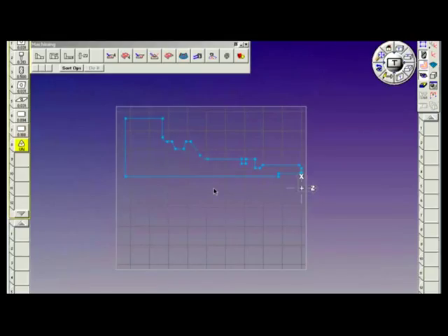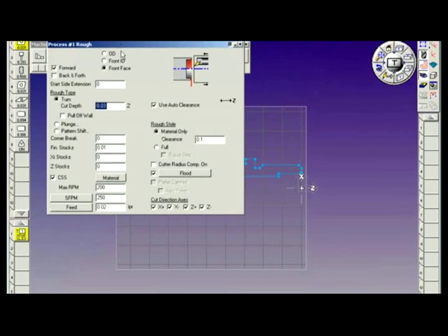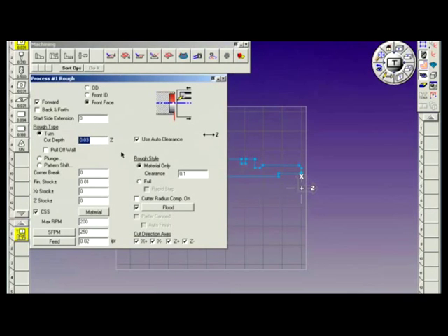The first operation is going to be to remove 100 thousandths from the face of this lathe part. This is done by dragging tool number 1 down to process tile number 1 and the rough turning tile on top of that. The process dialog window appears. We have a series of options. We have 3 choices for applying the machining: on the OD, the front ID, or the front face. We mentioned that this was going to be a facing operation, so we'll select front face.